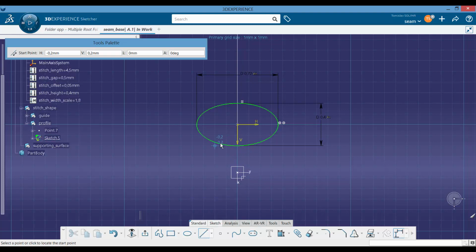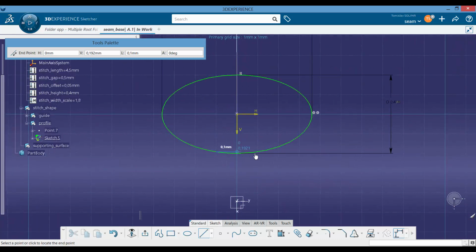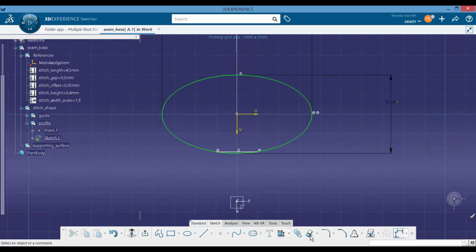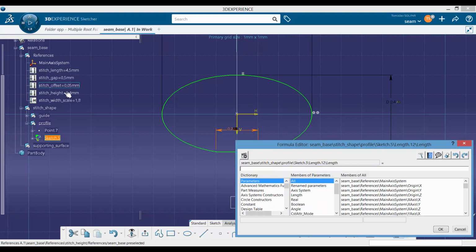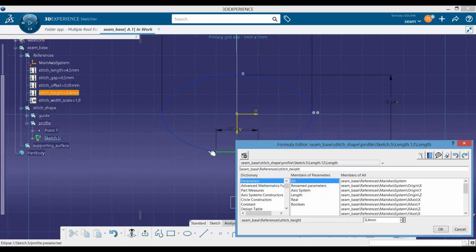Additionally, we will cut off the bottom. So we'll cut off, we can simply delete the lower part, and now we'll define this length here as well with a parameter. So we can select it even with the left button and choose the formula. The formula will be 75% or half, or whatever number we consider big enough so it is not visible underneath the edge of the element when the stitch is lying on the geometry.